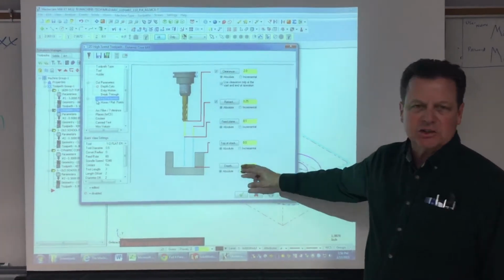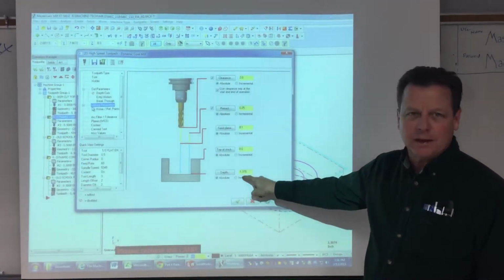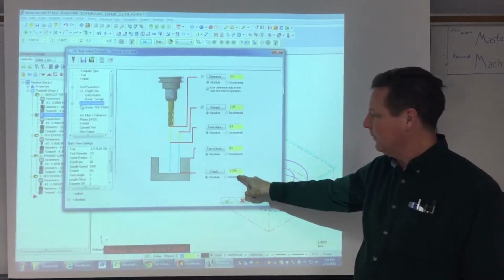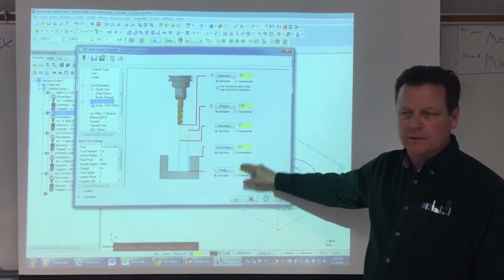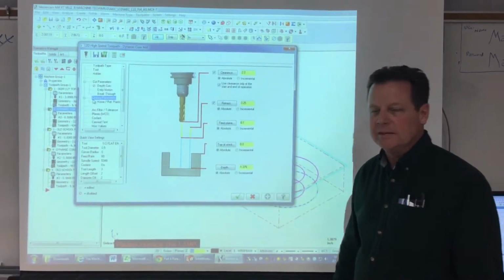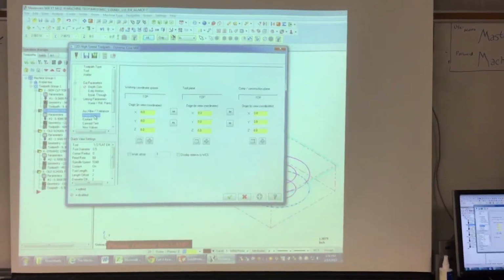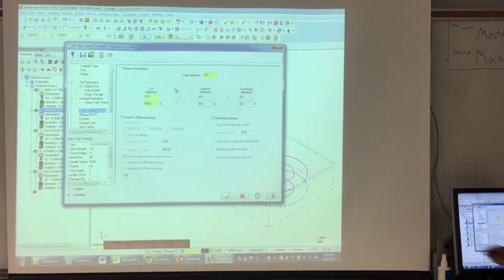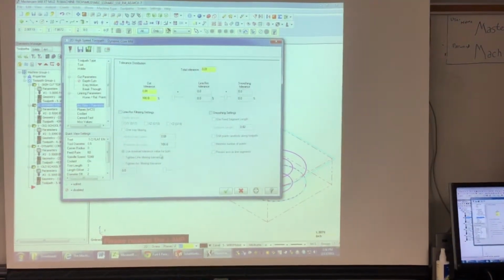This is kind of an experimental thing. That might not be what I want to do. I might need to break that up into 2 things to get this part done. But I have heard that you can go 3 times the diameter of the end mill down the side of a part and save lots of time getting rid of stock you don't need. Arc filter tolerance, I made that big so that Mastercam doesn't generate a whole bunch of unnecessary lines of code.